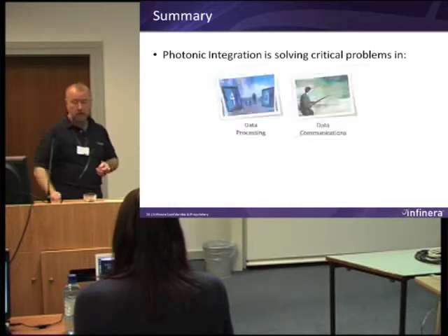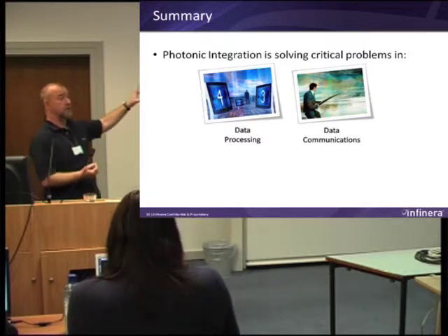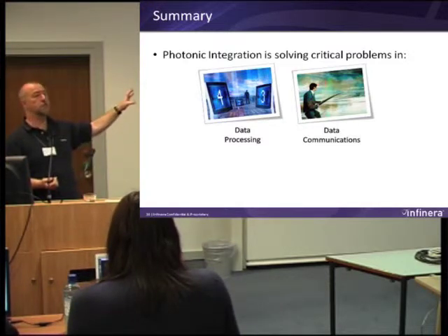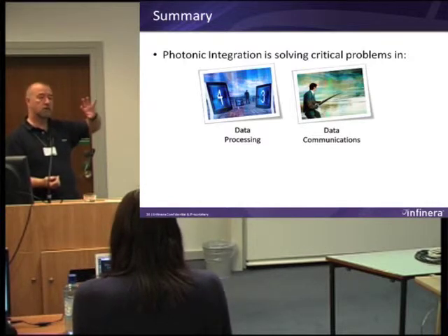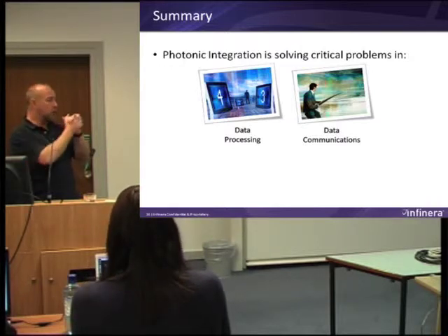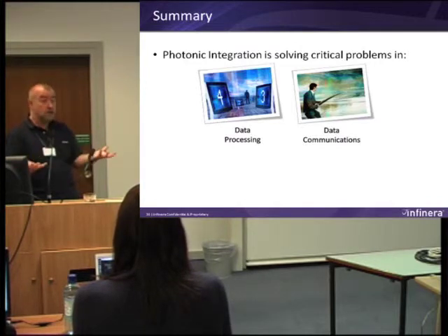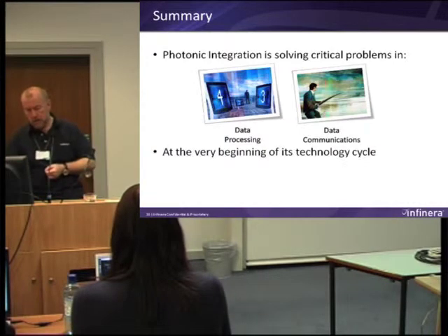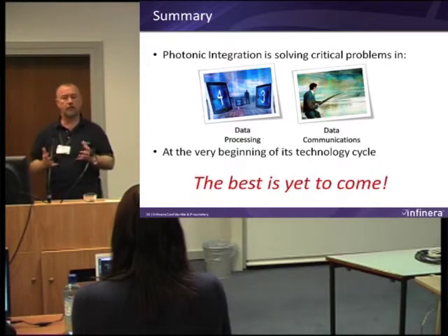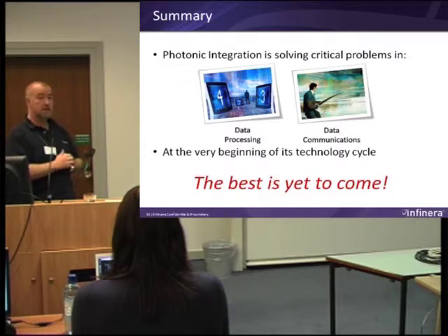So, just in summary, photonic integration is solving serious problems in data processing. I haven't covered those aspects, but the whole issue of optical computers is basically hinged around silicon photonics. Silicon, you can get it to work, but only over very short distances, on a chip or perhaps across a backplane. If you want to drive thousands of kilometers, you have to use direct band gap materials like indium phosphide. And it's at the very beginning of its technology cycle. I said we've almost got to the point where Intel was 40 years ago. So in the words of the famous philosopher Frank Sinatra, the best is yet to come. Thank you very much.